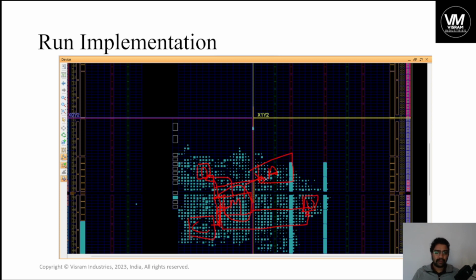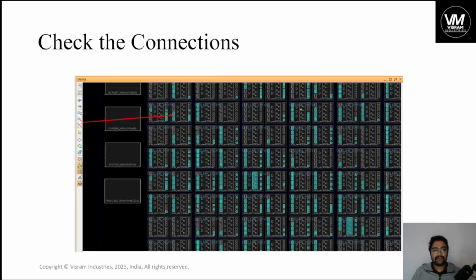And if you don't see any clock here, yes, some devices can be connected, some combinational logic cells can be connected directly to this, and they don't require any clock. But every sequential cell, a sequential device that requires clock, should be attached to the same clock for the entire design. So there is only one clock. So you can highlight.